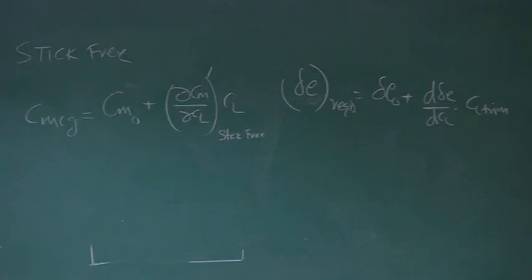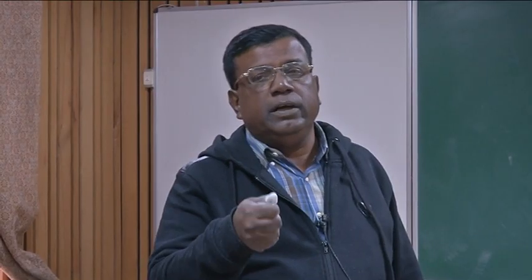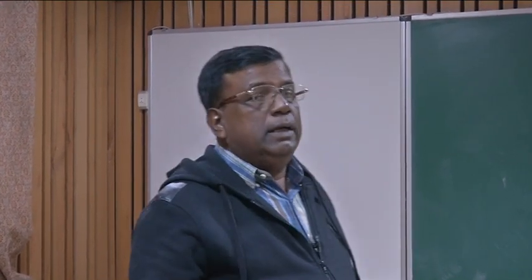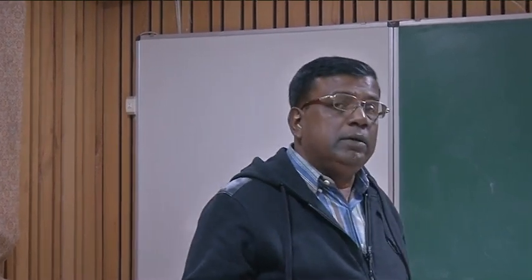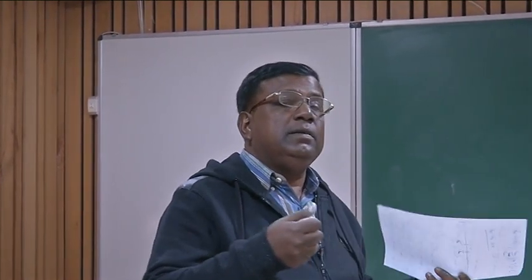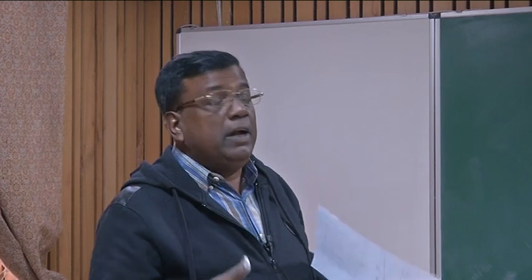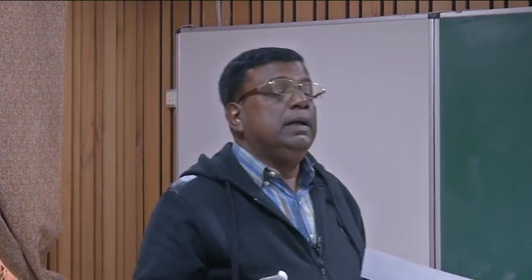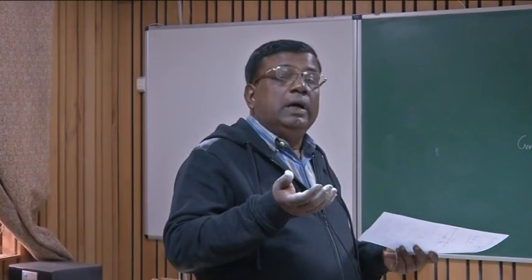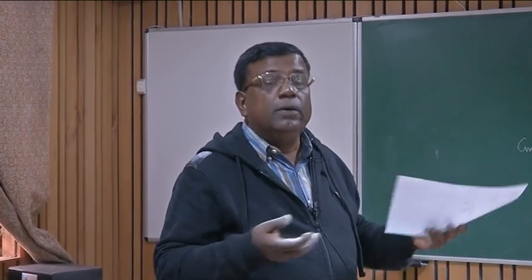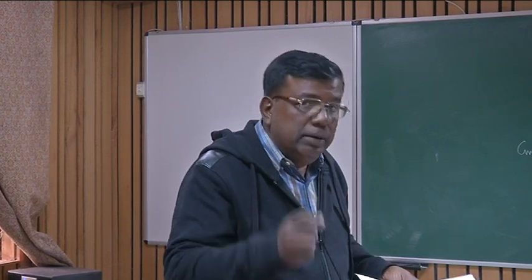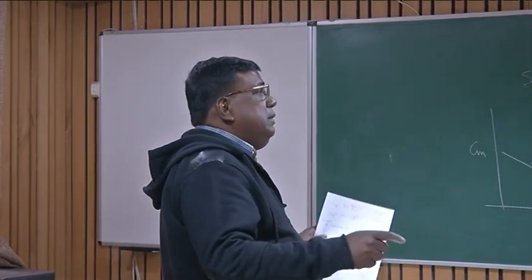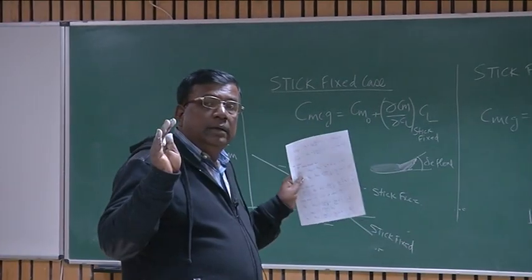I repeat, in one case, you take it to that 5 degree or 4 degree and fix it, lock it, stick fixed. Now we are doing one more thing, because we want to develop a stick force relationship with such deflections or speeds. So we are saying, let us also see that since the elevator will float, how much effort the pilot has to put through his force to see that it again goes back to 5 degree. Okay? But if it is 5 degree, it is 5 degree. Correct?